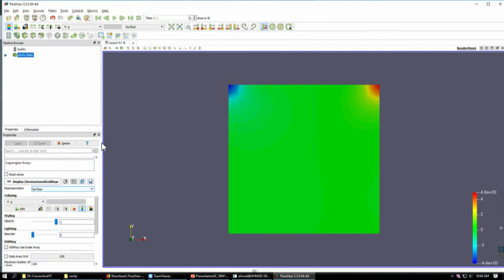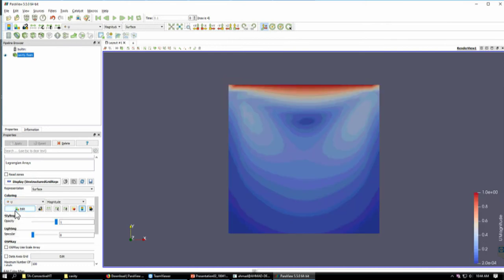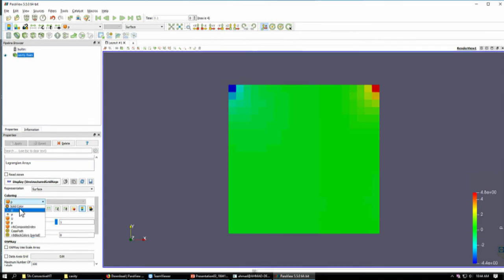So this is what is happening, and I am now explaining to you the different types of options you can use. When you click this coloring menu, a list of different variables comes out, and within them there is another one. Of course, U will be there, which is the velocity. You can view the velocity contours as well. And P, there are two P's. There is this P with a small dot, and then there is a P with a box. What's the difference between them?